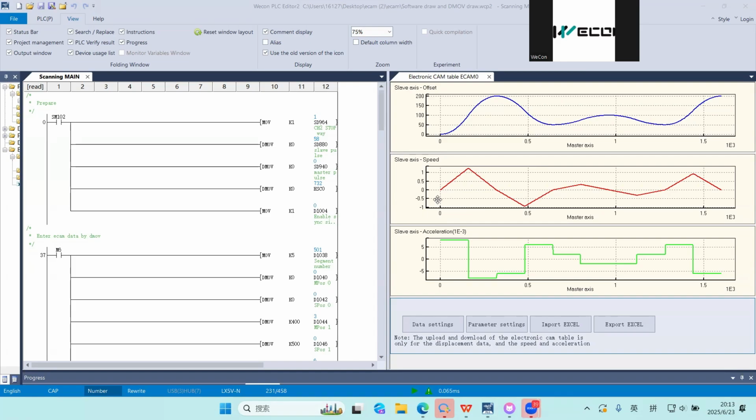Normally in cutting applications we use a non-periodic cam, but we need to use an external start signal. Usually, for example, every time the sensor detects the ice mark on our package, the slave will run one cycle, and in this cycle it will cut one time.